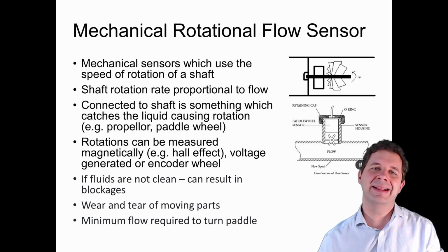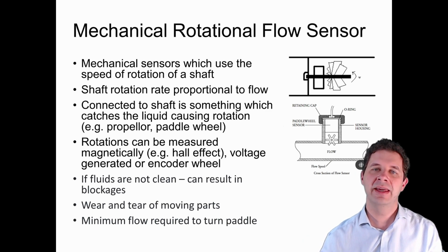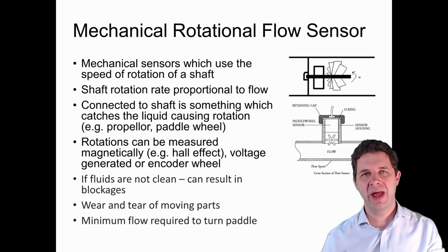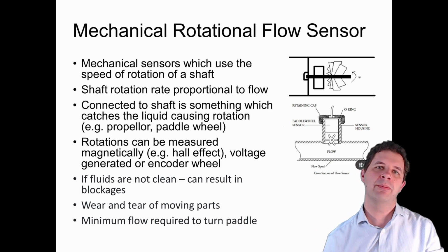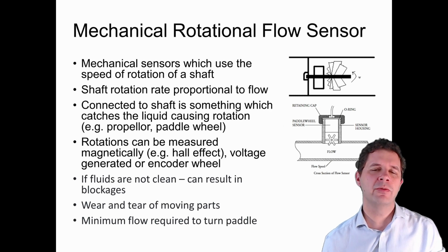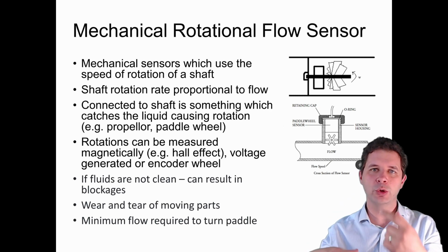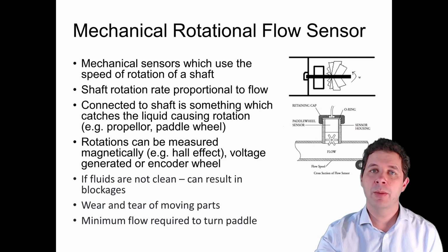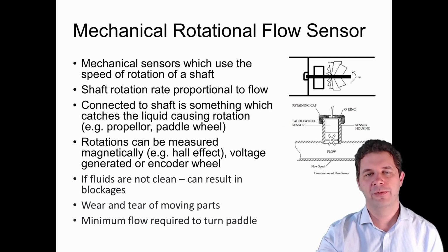If our fluids aren't clean, we can have blockages occurring here that would have a very detrimental effect. And we do have wear and tear. We've got all these moving parts here. We also have a minimum flow required to get our turbine or our paddle to actually turn in the first place, so it may not be very accurate or suitable for very low flow applications.